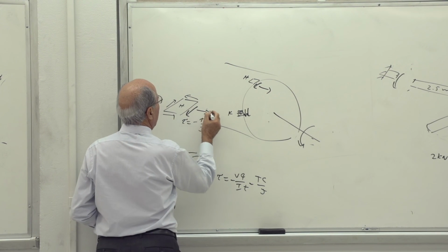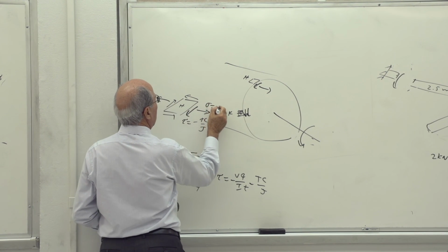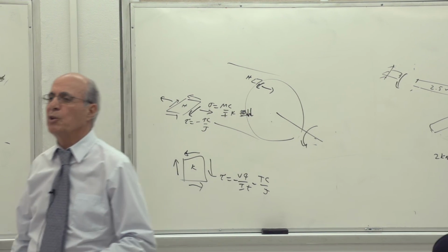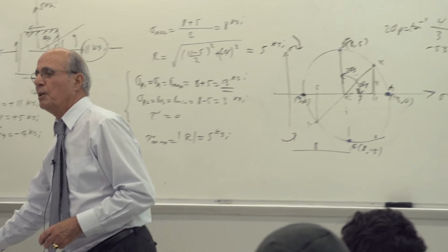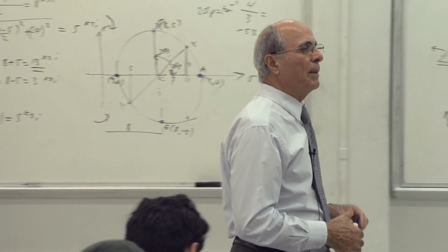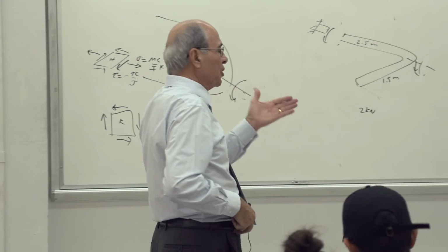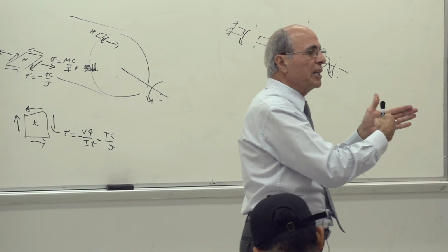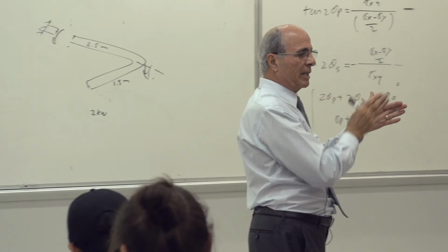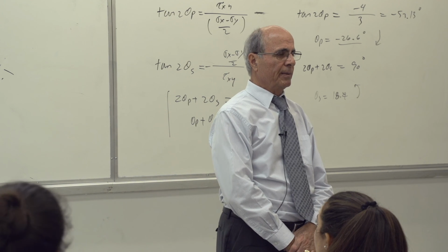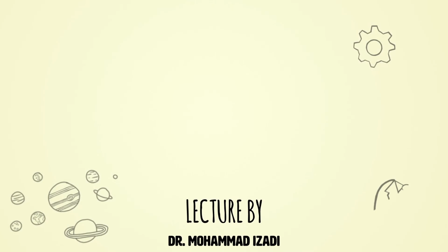That is the one where you get sigma equal to MC over I. That's all your stresses there. Those are the states of stress for point H and point K. Did you see what happened there? You just look at the cross section. You just draw your stresses perpendicular to the cross section or parallel to the edge of the point. Is that correct or not? Yes? Very simply.